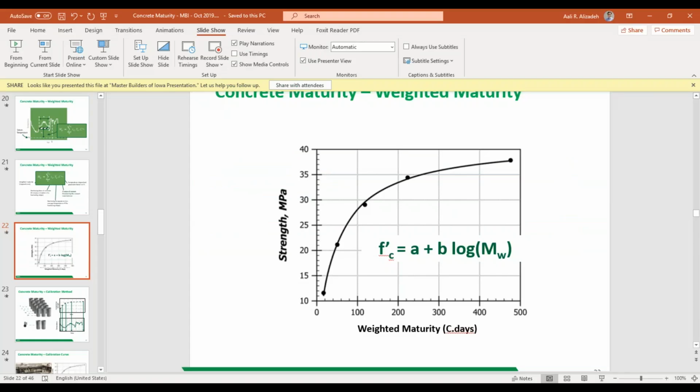It can vary from mix to mix, but as I mentioned, the rule of thumb, ASTM gives you 32 degrees Fahrenheit for cement type 1, and most people are using that as a good guideline anyway. So perfect. So let's do number 5 before we go to the rest of the presentation.